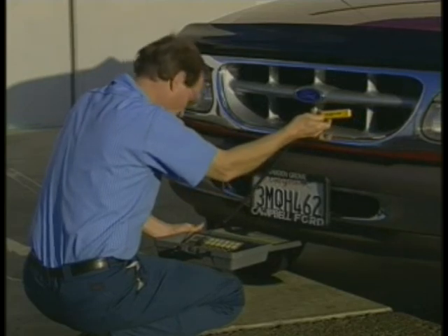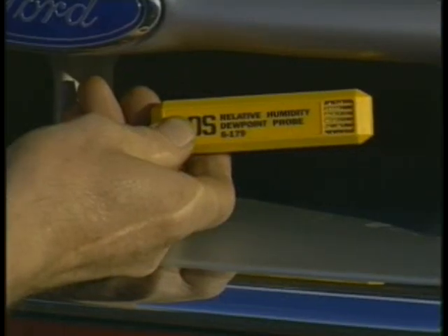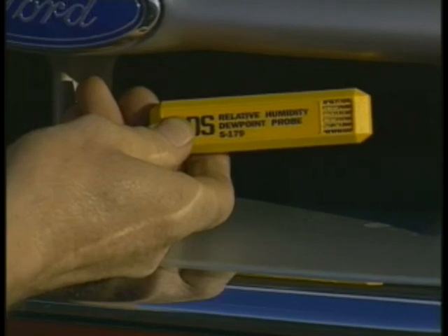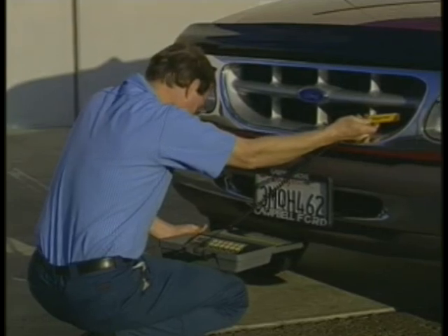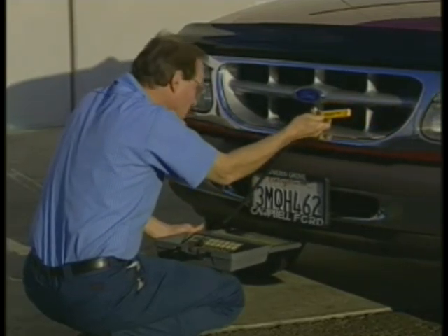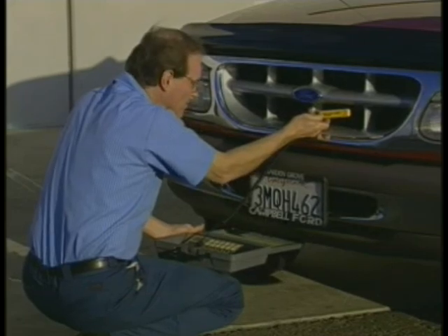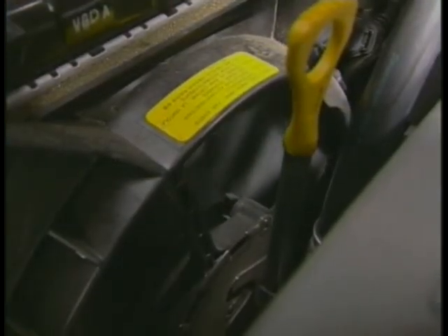Humidity is the amount of moisture that is in the air. Relative humidity is the amount of moisture as a percent of the capacity of the air to absorb moisture. Air with a low relative humidity can absorb more moisture than air with a high relative humidity, thus aiding the dissipation of heat. In automotive terms, then, air conditioning systems transfer the radiant heat produced by the sun that is inside the car to the outside air through the processes of convection and evaporation.